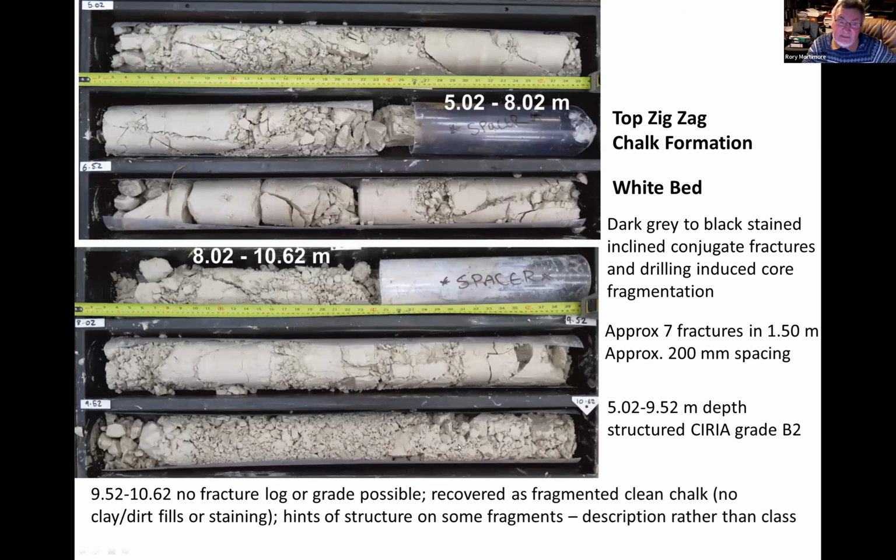And sometimes for the designers, over those intervals of rock, they need to know what sort of grade they're dealing with. Now, sometimes you can use camera logs down the boreholes and have a look and see whether what you think it is is correct or not, but you may not always have that, and you've just got to deal with what you've got there.